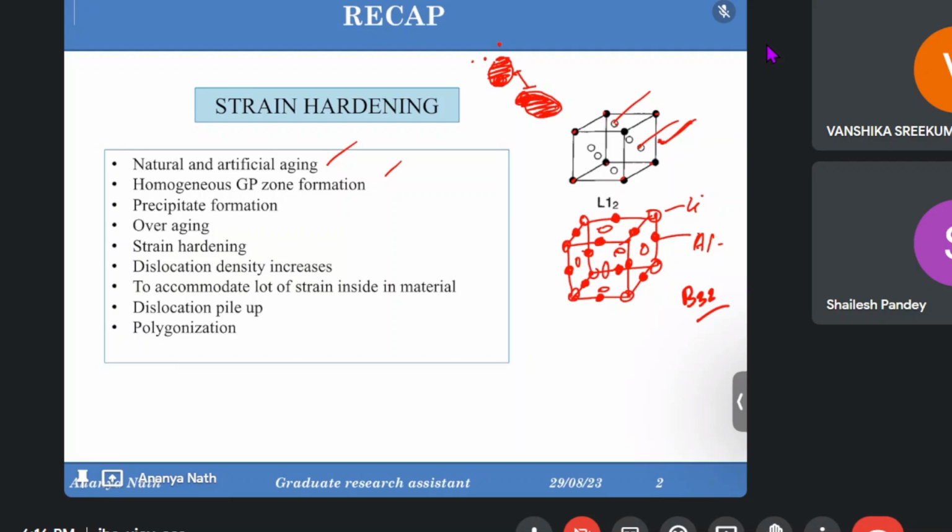So then the dislocation density was another topic. In aging, we were just restricting the dislocation motions, but we were not that much concerned about the dislocation density, because in heat treatable alloys, anyhow, by increasing the temperature or strain rate, we can control the dislocation and the solute atoms movement. We can make the precipitates form, and this is why we were not concerned about the dislocation density.